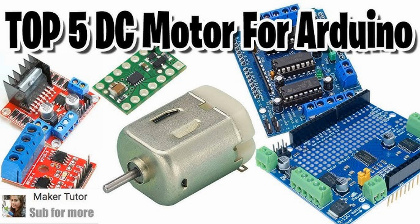Servo motor drivers with programmable control. Function: these servo drivers include programmable logic that allows users to define motion profiles, torque limits, acceleration, deceleration, and other parameters. Operation: the driver typically includes an embedded microcontroller or FPGA that executes a predefined set of commands or algorithms, allowing the motor to follow a specific motion pattern.